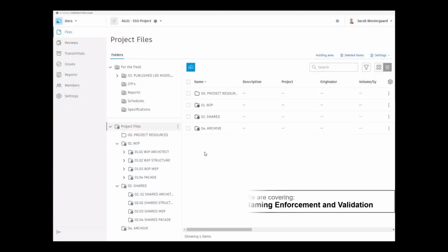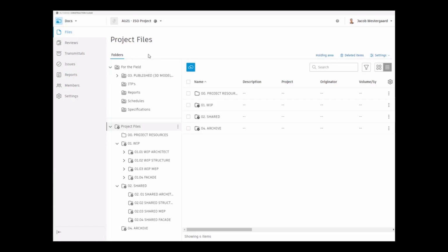We're now back within Autodesk Docs. We have our Plan folders and we have our project file folders. What's different now is that you have applied all of your naming standards, and we now see enforcement icons embedded into individual folders. These represent the folders we previously chose to enforce, and that means that every document we place or publish into these destinations will be checked, and if there are documents that don't conform, we will be required to either change the naming, send it to a document controller, or cancel the publishing.